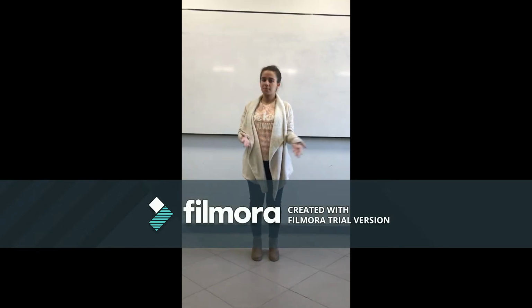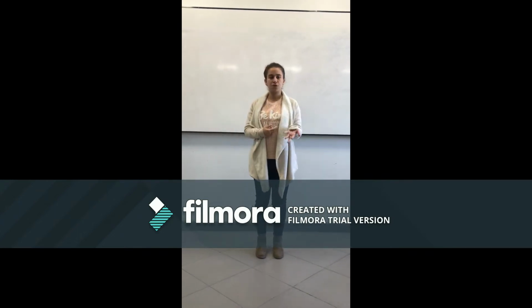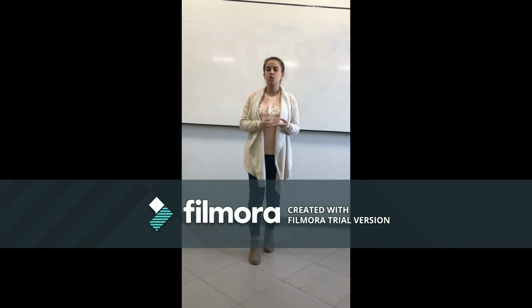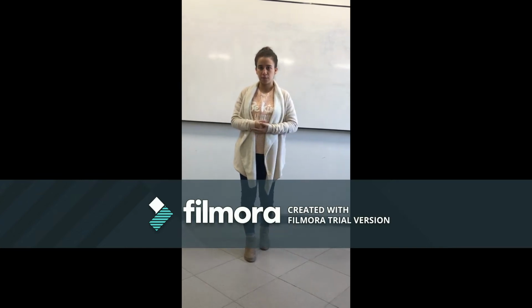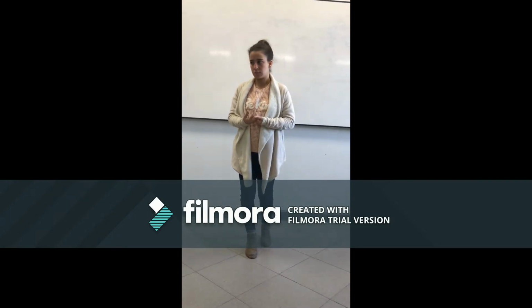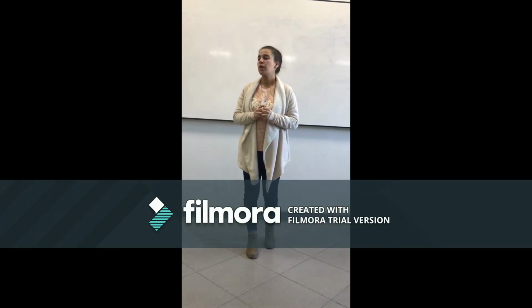Today I'm here to introduce an overview about our project. Our project is about lecture halls. We are counting the number of students entering the lecture hall and the number of students leaving the lecture hall using 2 infrared sensors. We also have 2 LEDs, a green one and a red one, ensuring the maximum capacity of the hall. When the hall reaches its maximum capacity, which is 9, the red LED is turned on and the green LED is turned off.